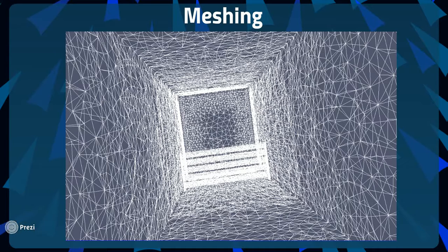On the screen, you can see the mesh used for the 90-degree barrier configuration. As you can see, the barrier inside the wind tunnel looks almost a solid white. This is because it is split up into many more subdomains compared to the surrounding wind tunnel. The reason being is that this is where most of the physics happens, so the solution must be as accurate as possible.